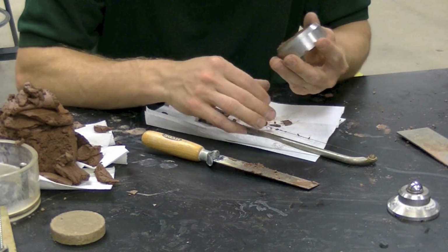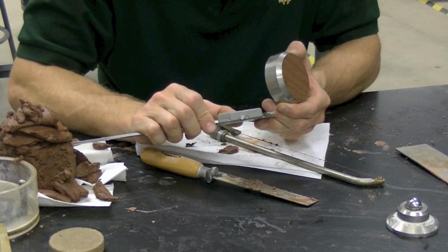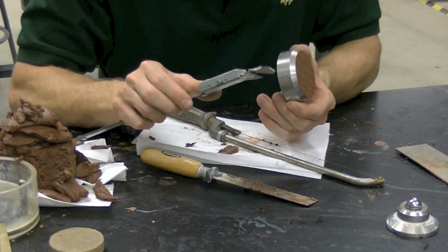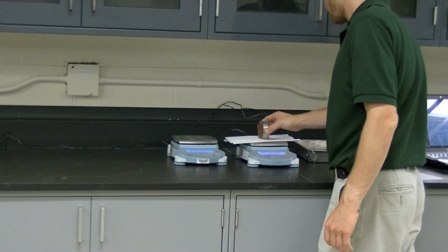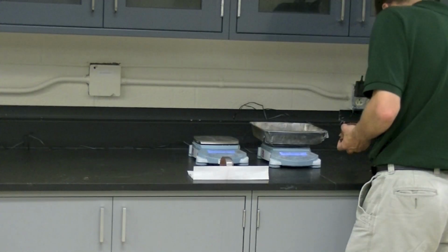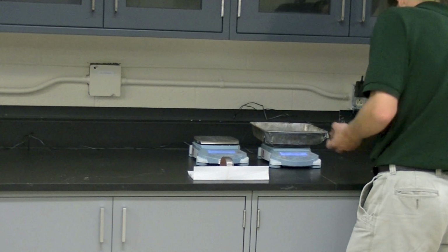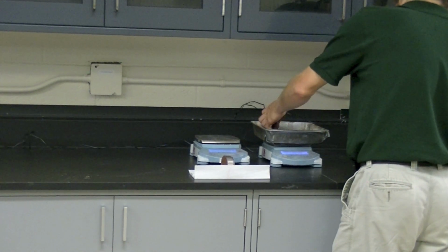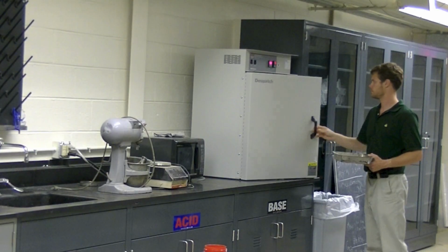Clean off the entire outside of the ring and beveled edges. Take 4 independent thickness measurements of the sample and average the 4. Weigh and record the mass of the wet soil and ring pre-test. Also weigh a tare and place a portion of the leftover undisturbed soil in the tare for a moisture content determination. Place the tare in the oven to dry at 110 degrees Celsius.